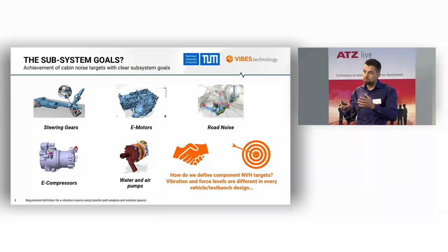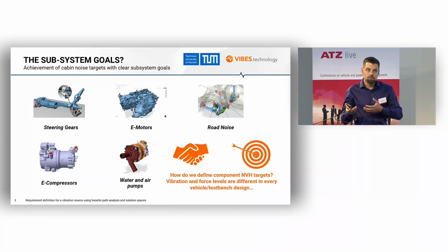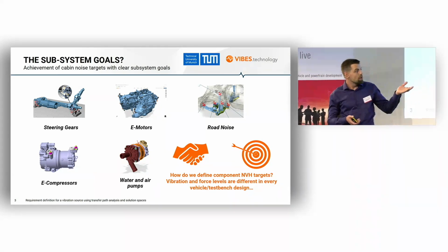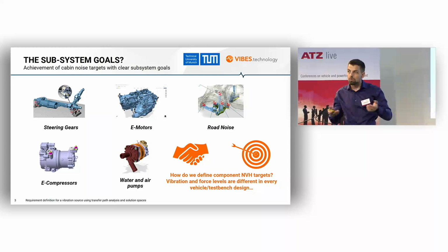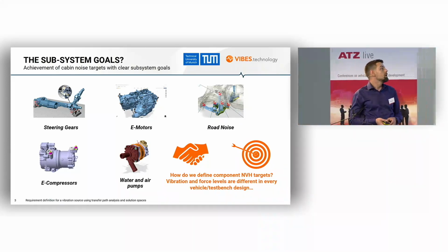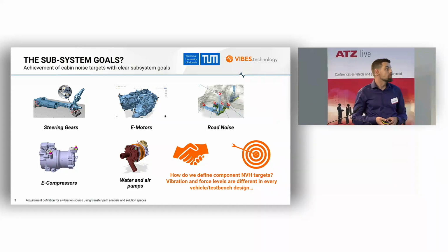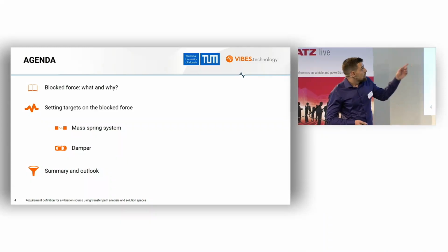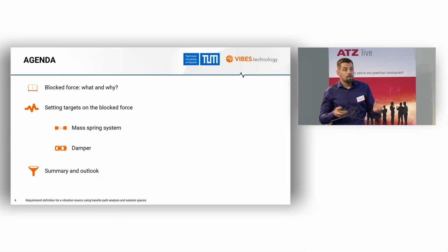It's a highly coupled system, so your test bench assembly is going to have very different resonances than your vehicle, and you are faced with this challenge of how to define meaningful component targets for the structure-borne sound path.